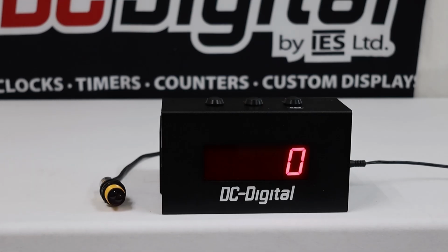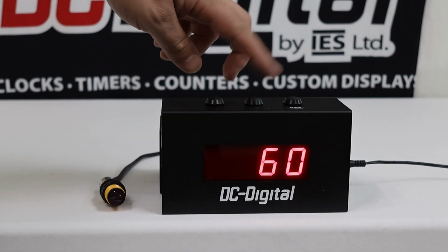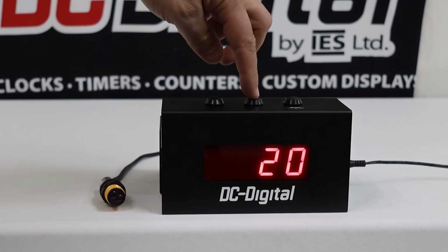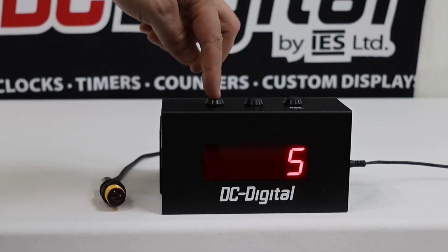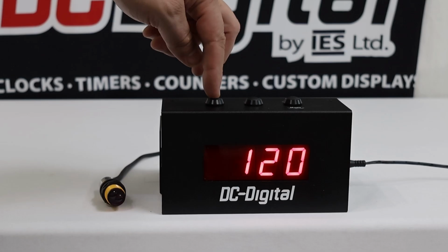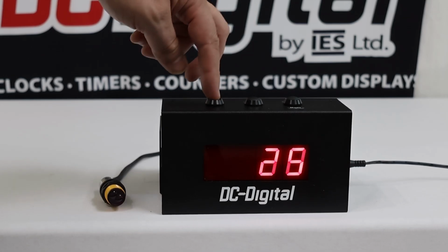Thank you, Ian. Here we have the rate display currently with 0 products. The photo eye is what is pictured on the left there in yellow. That is what determines, or measures, the parts as they move across it or underneath it. To set up the rate display, you set the interval of time. Currently it's set to 60. We can subtract by 5-second increments all the way down to 5, or increment all the way up in 5-second increments up to 120, and it does roll around.